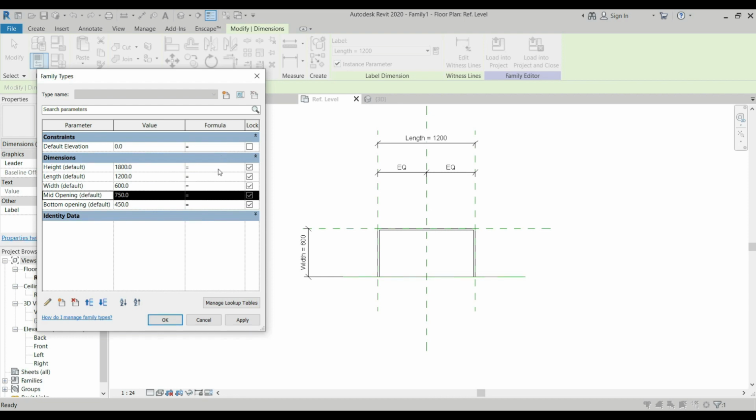So there. So formula, if you want to have a formula here, the formulas that you're going to use are the same as in Excel. For example, the only editable one here is the inside opening or inside length. So you can add the inside length parameter, then put a formula. Or the thickness of your material. So for example, you want a 1" or 1/2" plywood. So you can use a formula here.